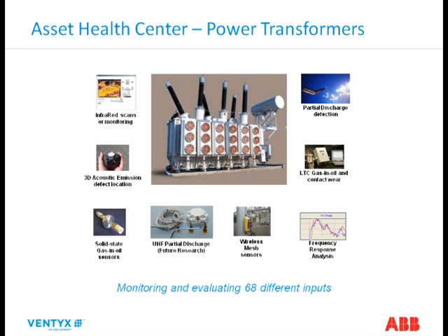If you look at the middle two, the acoustic emission and also the load tap changer, gas and oil, and contact wear, that is focused on LTCs, the load tap changers, and we're doing some development work with a utility in Canada around the acoustic signatures associated with the operation of load tap changers and how we can benchmark that and then track if there's any variation.